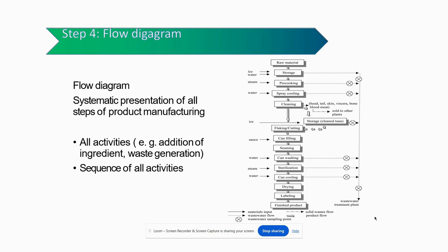The process flow chart for pasteurized milk, condensed milk and paneer will be different. So we need to draw the process flow chart as per the procedure, to ensure that the proper plant design and plant layout are implemented in the process, whereby the product goes in a sequential manner till the end product point. So the fourth step is the development of the flow diagram. Then the fifth step is verification of the process flow diagram on site.